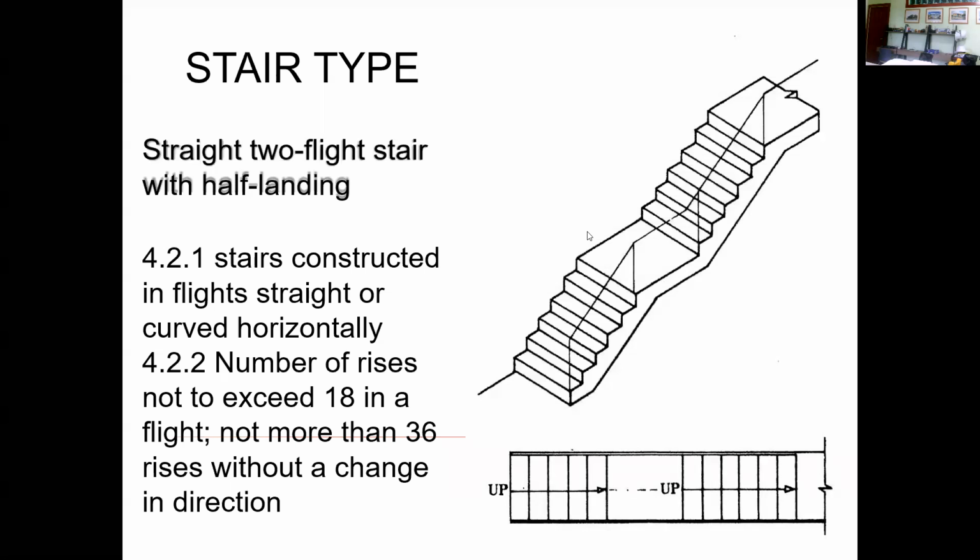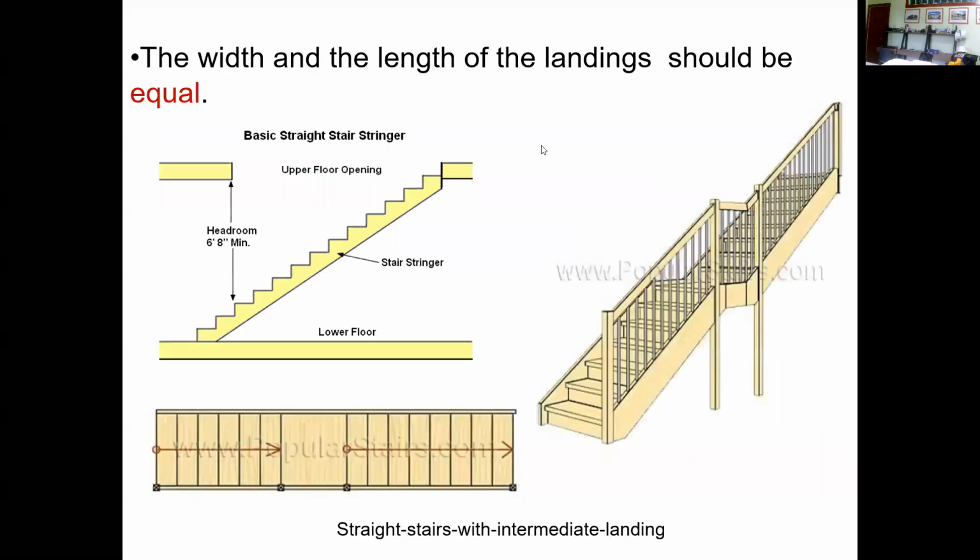So this is another type of stairs. The width and the length of the stair should be equal. As you can see, we also have a headroom of about 6 feet 8 inches, or about 2 meters minimum, for headroom.